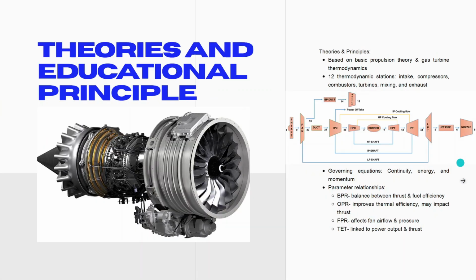Next are the theories and educational principles. This study is grounded in basic propulsion theory and the thermodynamics of gas turbines. By applying continuity, energy, and momentum equations across 12 thermodynamic stations of a turbofan, from intake, compressors, combustion chamber, turbines, mixing, and exhaust, the tool simulates real engine cycles.